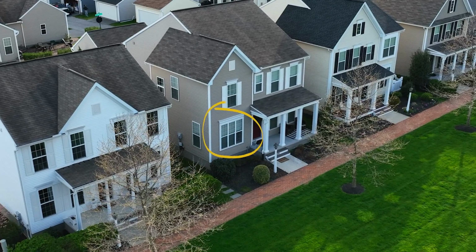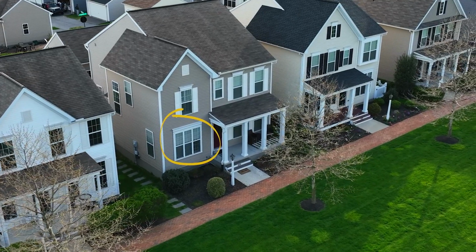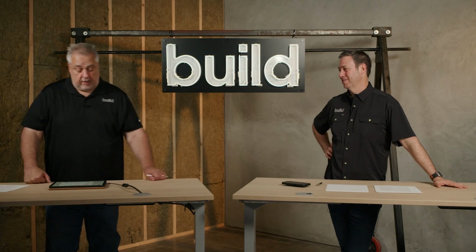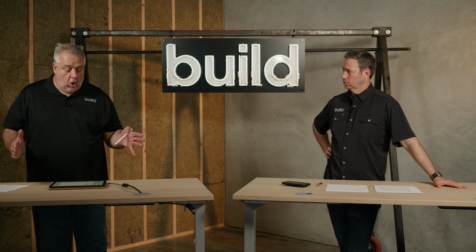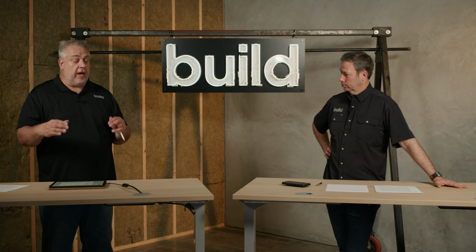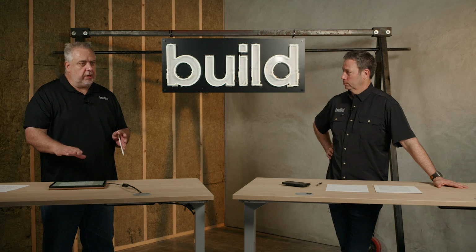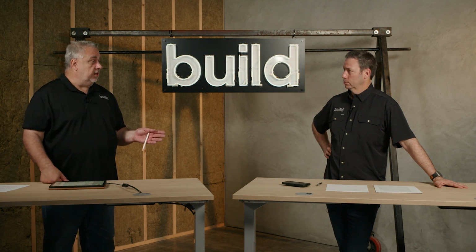They're very vulnerable. And that is, in the production builder's world, like those sliders on the first floor and a 2-story wall are killer. They are really prone towards leakage. Yeah, that's right. Exactly. So 2 to 1, 1 to 1 is okay. When I start getting less than 1, I need to really start thinking about the flashing details on the window. I need to start thinking about who's doing the flashing details on the window.